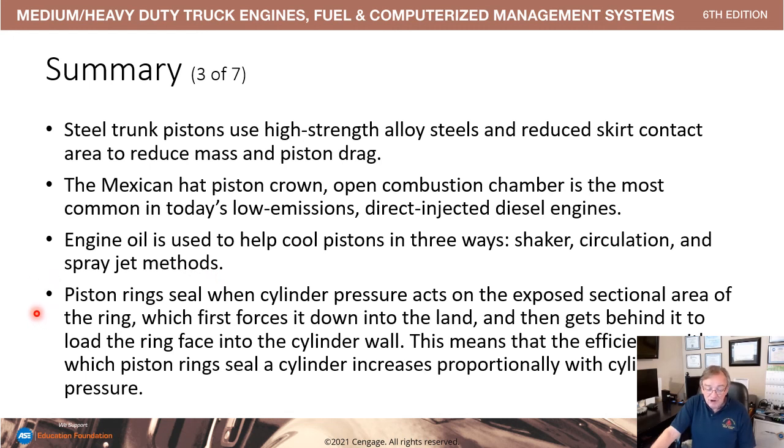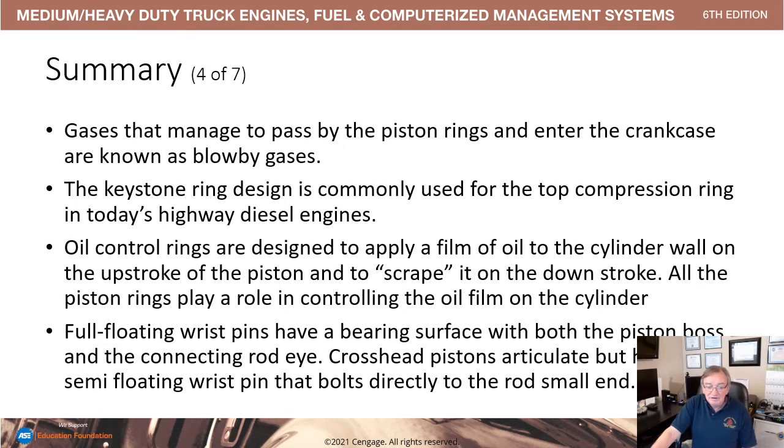and piston rings. Piston rings have such a critical contribution to cylinder pressure and lubrication, and we're going to be showing you that as we remove some rings and install them, and understand how the rings are critical to the life of the engine and holding the cylinder pressures. We understand the gases, the keystone ring design, which is common for your top compression ring. Now keep in mind your top compression ring is the hottest of the two or three based on the configuration, so it has the most amount of thermal stress on it.